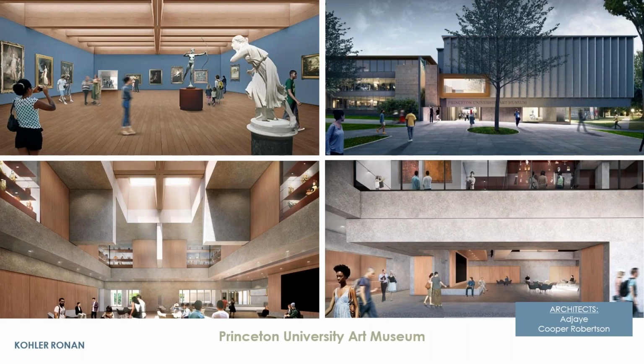Another project, the Princeton University Art Museum with AJ Architects and Cooper Robertson. Again, this is a brand new addition and a restoration of an existing building. Again, complicated artwork, complex building structures. We're using a lot of new construction technology as well, timber-based and concrete, a mix of all of that. So when you're working with such environments, CFD has been really helpful for us to figure out how we're distributing airflow, where we're returning from, where we're supplying from, and are we maintaining temperature and humidity continuously.